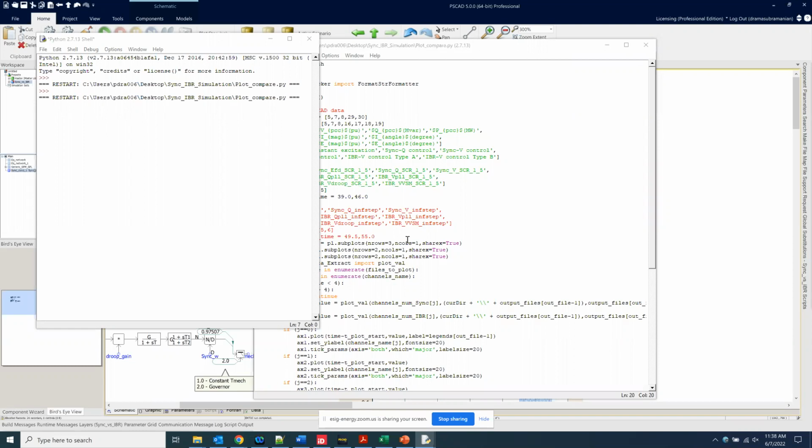So now, if the plant controller is slow and you don't have that voltage control at that inverter level, since it is on active power control and reactive power control, when you have a change in short circuit strength, when you have a change in phase angle, there can be an increased chance of instability occurring. And all our traditional grid following inverters work with that active power control and reactive power control at the inverter level.